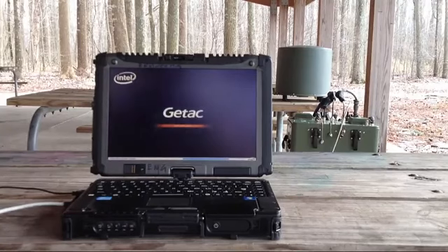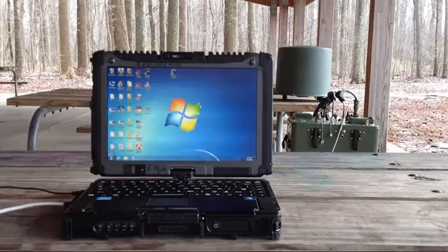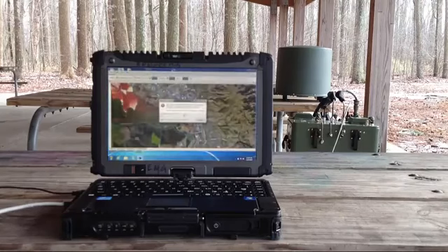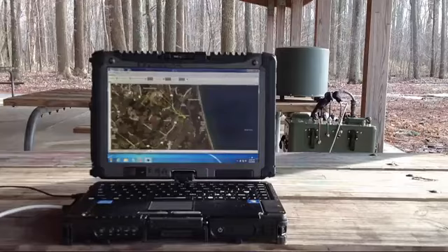After the Blackbird NextGen client application is launched, it takes a further half minute for the Blackbird NextGen server to finish initializing and be ready to accept a connection. When the server is ready, the client automatically connects. Once the Blackbird NextGen server has finished initializing, it continues running whatever task it was running when it was shut down. In this case, I had the 903S configured to survey a range that includes the 900 MHz ISM band.